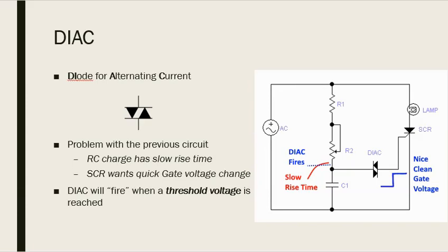Now, there is a problem with that. If we look at the circuit, when we charge up a capacitor, it has a slow rise time, and SCRs don't like that. They're going to have trouble turning on. They could overheat. They could have all sorts of issues.